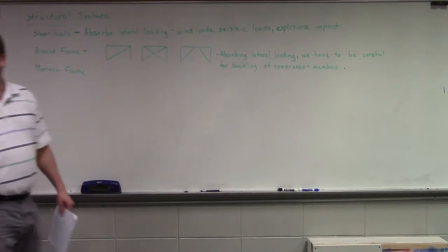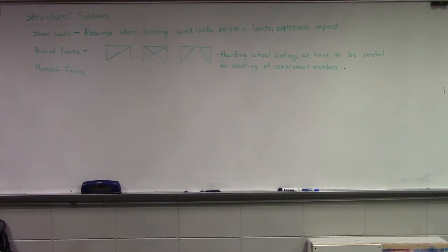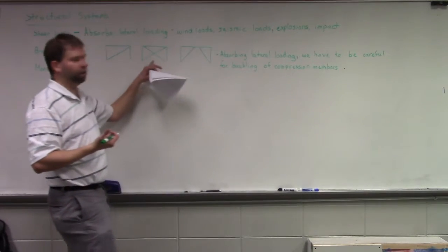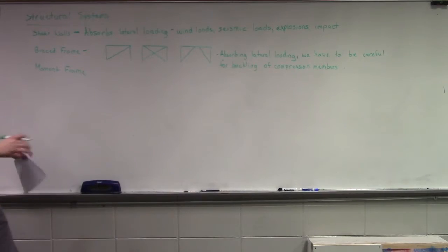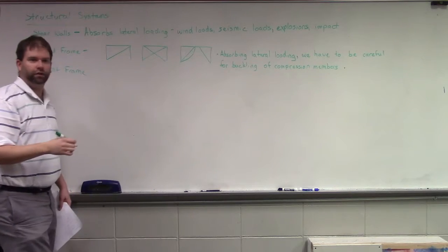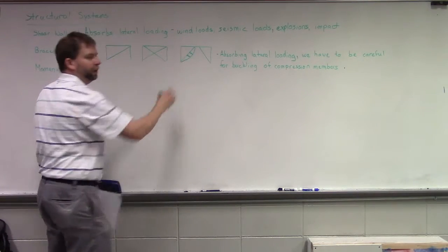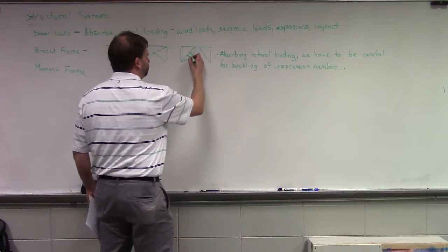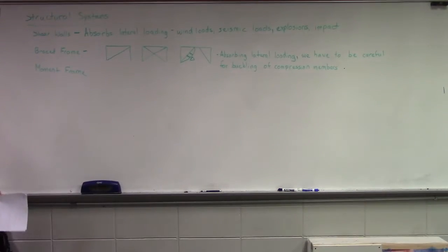Do you remember what buckling is? We haven't done really any homework problems with them, but I've had you read a couple little sections, one in the axial load chapter, and then a portion of chapter 3 on shear and bending talks about buckling. What is buckling going to do to our cross bracing? Yep, as Terry said, it's going to blow them out. It's going to start deflecting like this, and get to a point where the material itself will actually fail. Typically some sort of shear, bending, or combination of shear and bending causes that failure. So that's what we're interested in there.